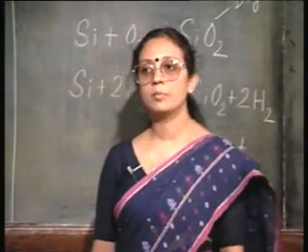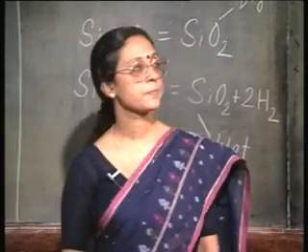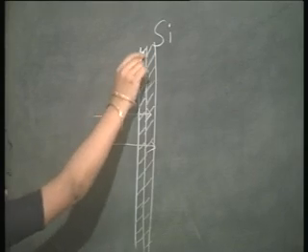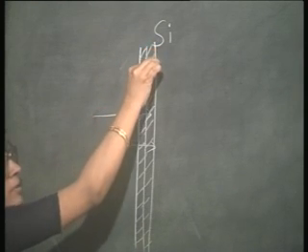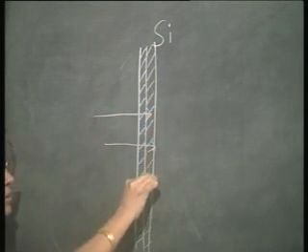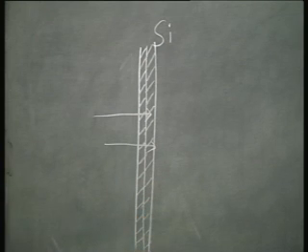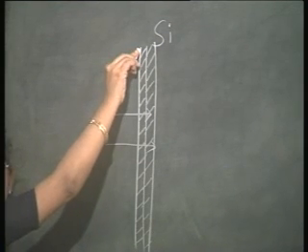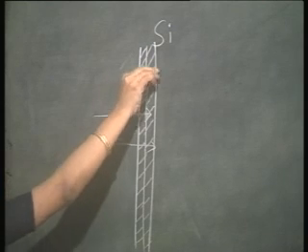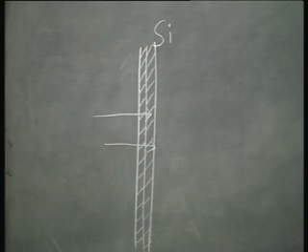Do you understand the fallout of this? In case of thermal oxide, therefore, you see oxide is growing in this direction. That means the interface is not the original surface. Do you see? The original surface was here. Now, the interface is here, it is not the original surface. What is the advantage?